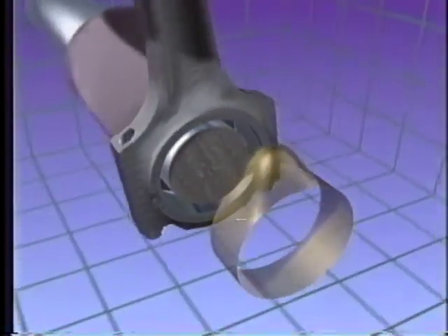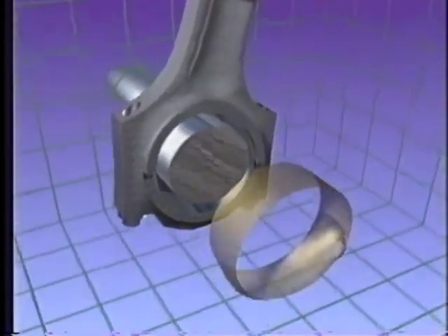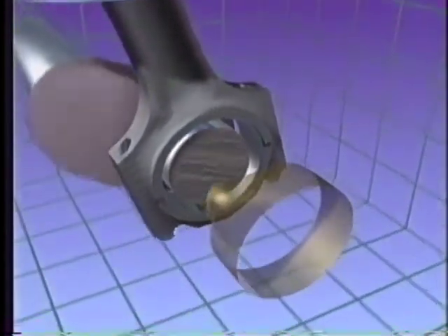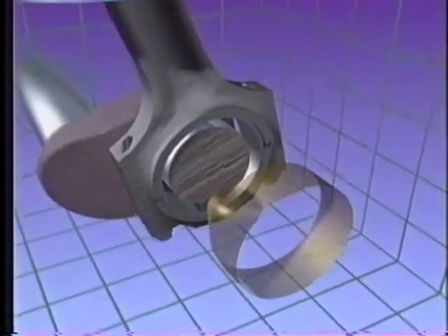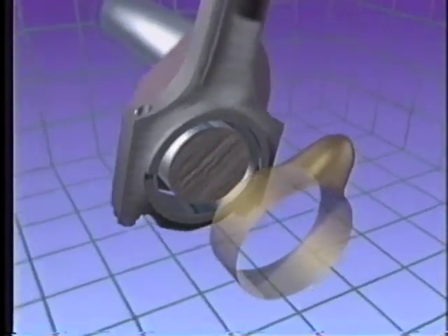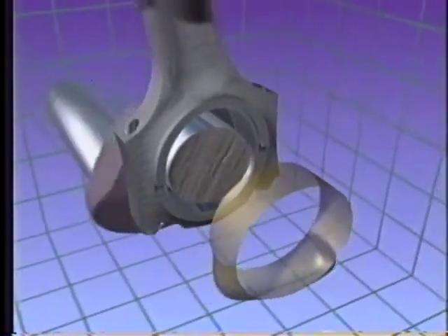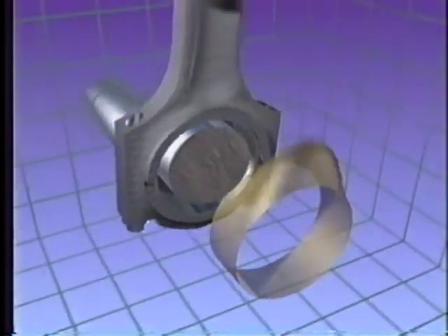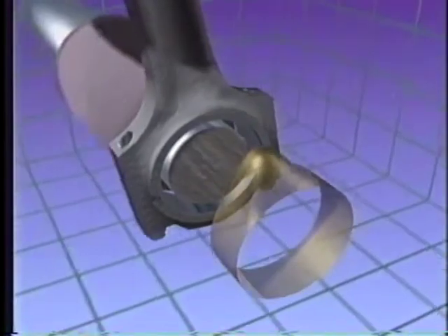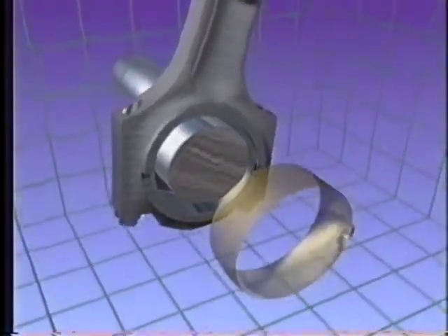Now you see the pressure of the oil film represented by the height of the pressure peaks. Excite can take into account the influences of oil supply ducts and grooves, of split lines of the bearing shells, and also of pin misalignment, giving the engineer all the data he or she needs for the design of highly loaded bearings.